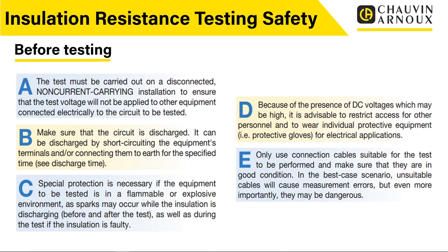So it is important. Don't just think that the test is limited to the space that you're working in with the cables in front of you. If you're testing a cable and that cable goes 100 meters away, you could potentially be injuring somebody that is 100 meters away as well. So we do need to think about those precautions.